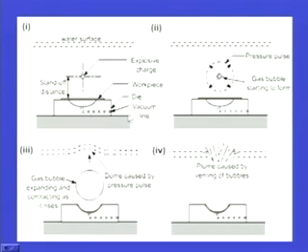So, why is the vacuum line required? It is required in order to suck the air. We have seen that there should be no air inside the die cavity. So, we may use a vacuum line or we may suck it by some other mechanism. There should be no air inside the die cavity, it has to be removed. Then this is the die, there is a vacuum line. Then this is the workpiece.